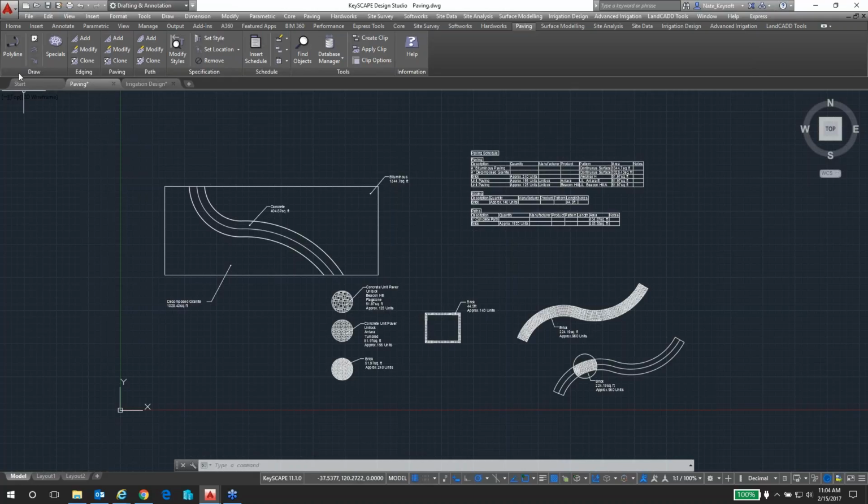And it's probably a good time to point out the power of using polylines in your construction when you're drawing outlines, you're laying out sidewalks or paving areas or any geometry really. Polylines, I think, are much more dynamic. Drawing with closed polylines ensures that your drafting is a little bit tighter. When you're trying to determine a boundary, you're not messing with endpoints and trying to reconnect things. So I always try to draw with polylines, or if I draw with lines, I'll try to join lines together to create polylines using the p-edit command.